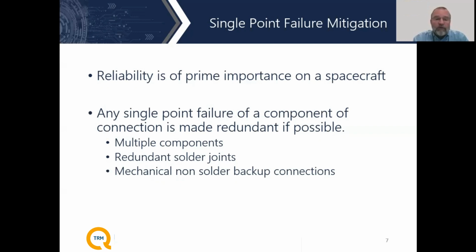That has to do with whether it's a redundant solder joint, or making sure that the layout, for example, if we're going to use a plated through hole as a via for a PCB, has several of them. This way, if one section of the board begins to be damaged or degrade over time or delaminate, there will still be a connection.